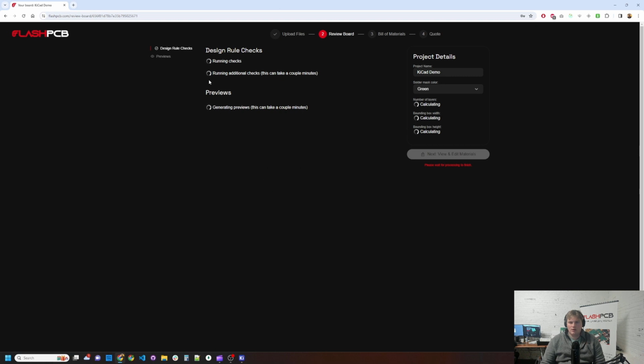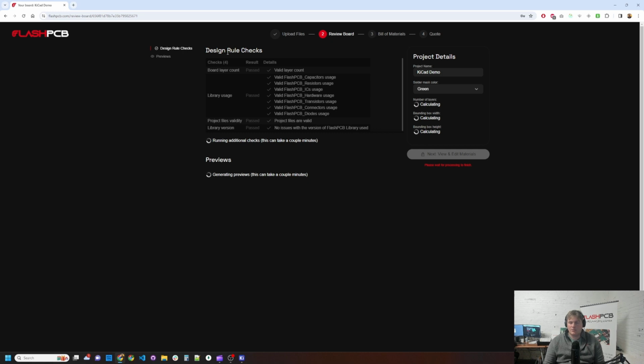Once you hit Submit, we start going to work on our end. First, we'll do some design rule checks. So this is making sure the board's actually manufacturable, so that once you get a quote, we're not going back to you and saying, hey, could you please change this? This doesn't work with our manufacturing process. We check all that here for you now. And if there are any issues, we'll highlight them in the previews so you can go back and fix those and make sure that you're getting a board that we can actually manufacture. So I'll come back to you in a minute or two once this is finished running, and we'll have a quick look through the previews, and then we'll go onto the BOM as well.